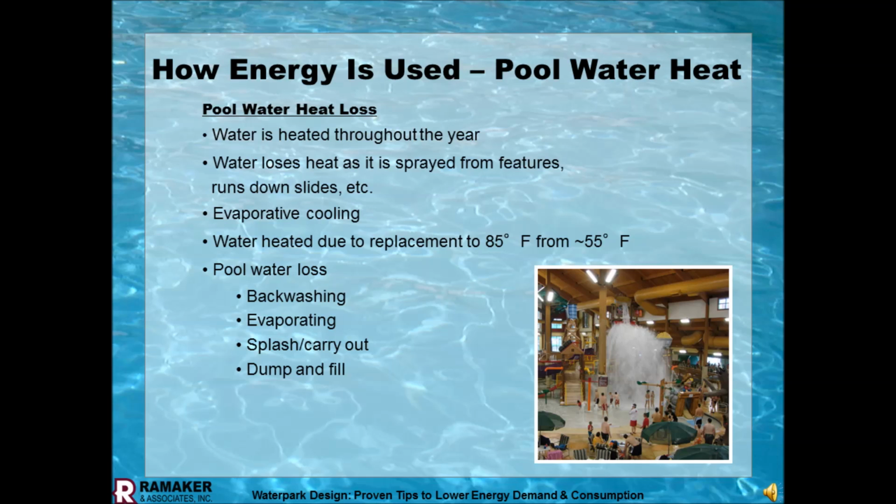Other additional ways that they're losing heat is with the backwashing of the filters. What volume of water are you dumping down the drain? When you're dumping water down the drain, you're dumping heat and chemicals. So can we reduce the backwashing? Evaporation, I talked about the spraying water, but can we go on to using pool covers? That's a method. I'll get into that a little bit later here. Just in essence, what can we do to reduce that evaporation?